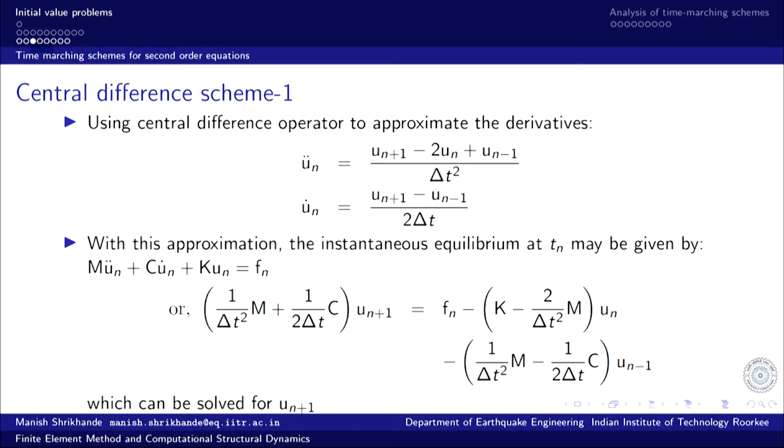So, very small time steps are of course required, and the choice of small time step is offset by the efficiency in computation. If damping is small and the mass matrix or inertia matrix is diagonal, then the computations can be implemented very quickly and efficiently.